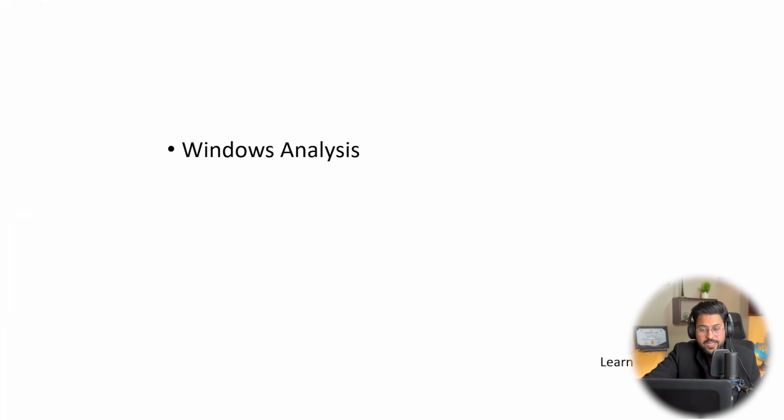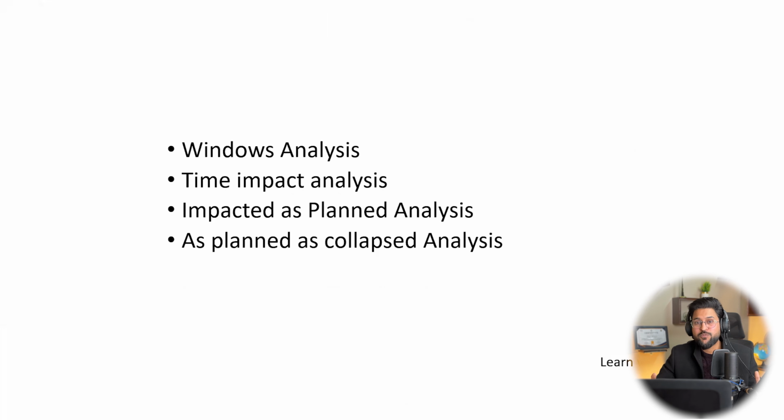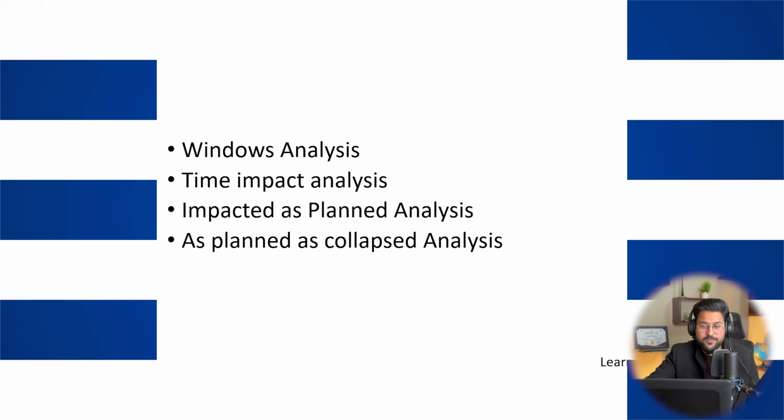There are windows analysis, time impact analysis, impacted as planned analysis, and as planned versus as collapsed analysis, in which you make forensic schedule analysis and many things are involved. This is the most advanced level of planning, and I'm also offering this as a separate course, so that you can become a senior level planning engineer.